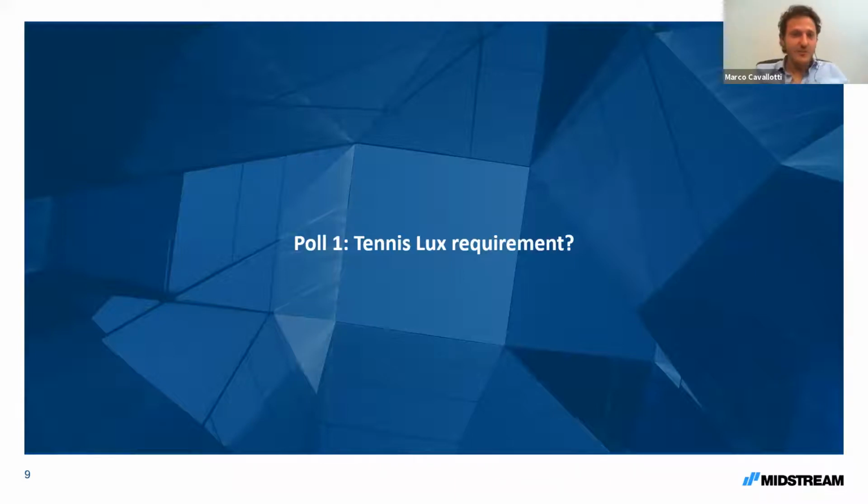Yeah, definitely. So 500 lux is the requirement we're going to follow in this session. Just some examples: 50 lux could be a loading and unloading parking area. 150 lux could be a private tennis court for training purposes. And 1000 lux is definitely more related to the UEFA regulation, very high level with camera broadcasting requirements. So we can start with our session.